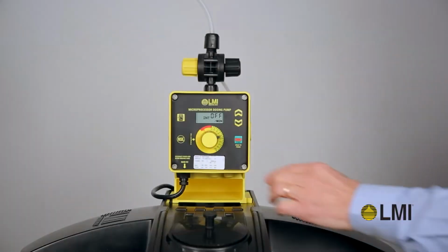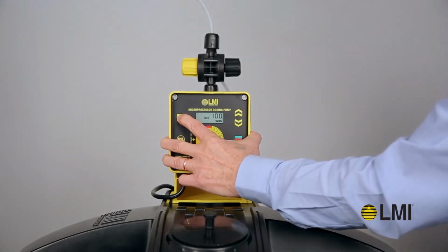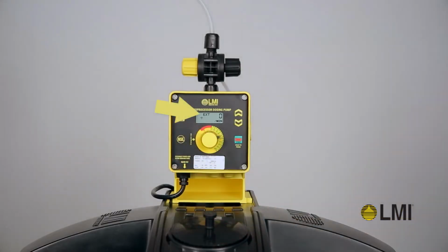To access the external mode on the B9 and C9 pumps, press the mode key for 3 seconds. EXT will be displayed on the screen confirming the pump is in external mode. You can now use any of the external program options to pace the pump. The factory default program of your pump is set to pulse divide with a divide value of 1.